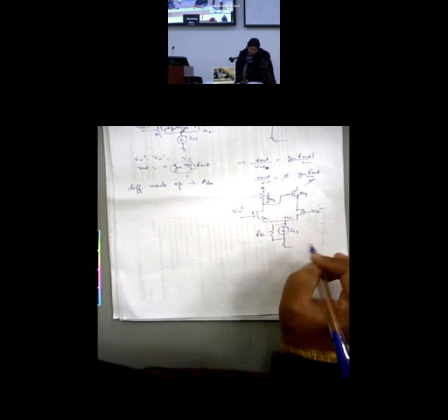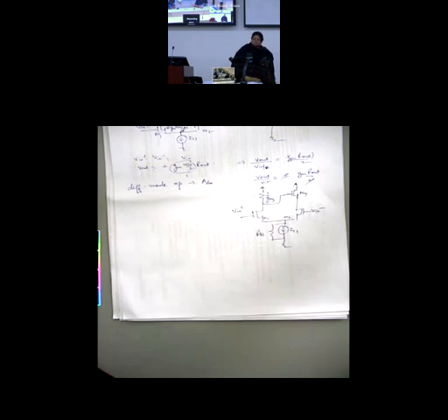And this is ISS whose resistance may be RSS. This is equivalent to a current source with an RO. M4 is equivalent to a current source with RO. So current source, this is source and this is drain. Current flows from source to drain.